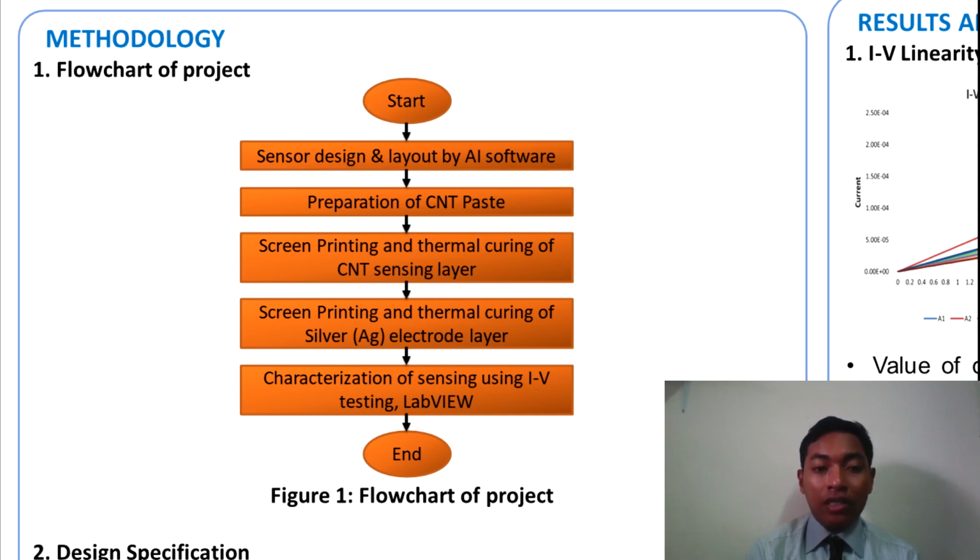Following that, the printed layer will be burned at specific temperature to facilitate drying. IV testing will be performed on the printed sensor for characterization. The data from the characterization will be collected for research purposes.